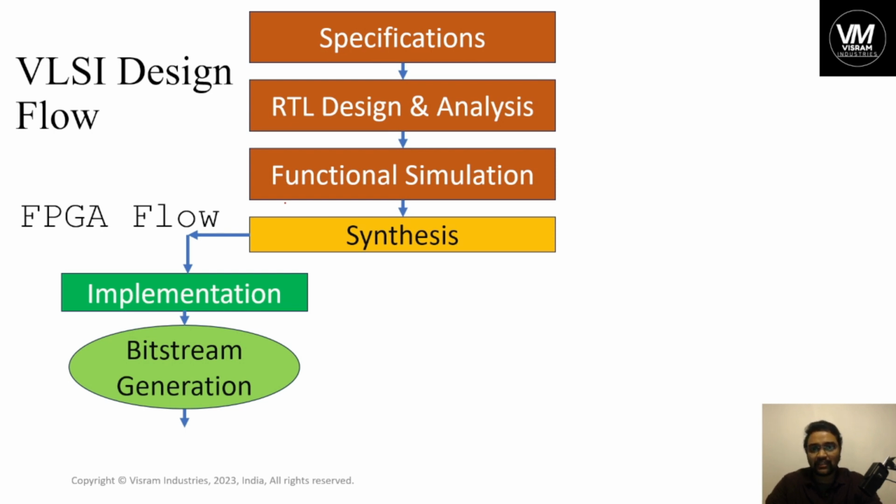If that is not working, actually we have discussed on day 9 of this training, you can see the actual FPGA design flow, where if you find any errors, you should come back to the specifications and start from there. Or if you got some errors at functional simulation, you can come back to the functional simulation and check it again, and then start doing implementation.